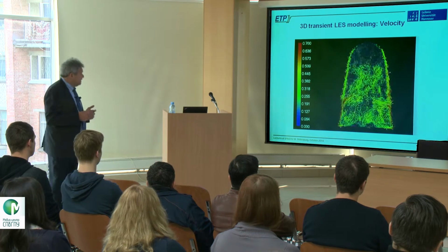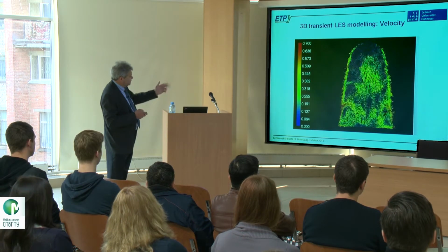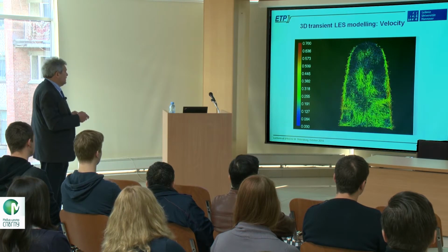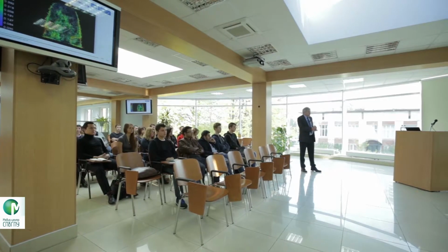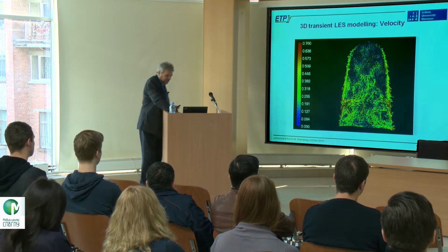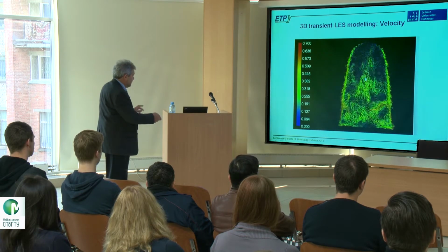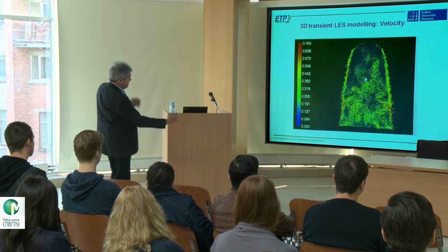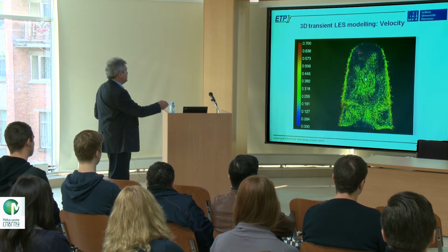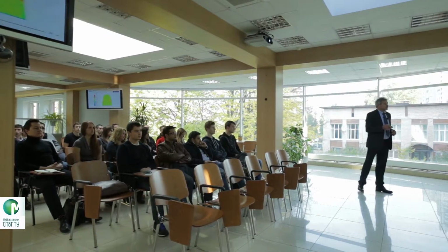Here you see finally the melt flow in such a melt in the cold crucible. You see very intensive flow, more intensive than in the conventional furnaces, as I have shown before. Here you have one small vortex downstairs. One vortex, you can imagine this is a kind of ring here, round. So one vortex here, and a little bit smoother and wider here, which pushes the melt to the top here. And the next shows the temperature distribution.